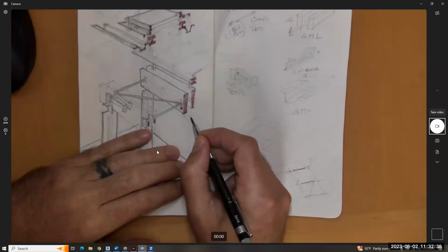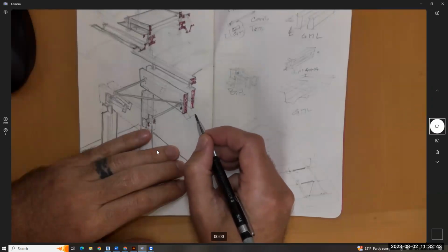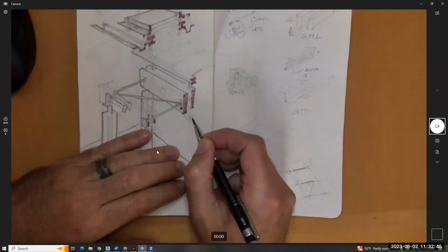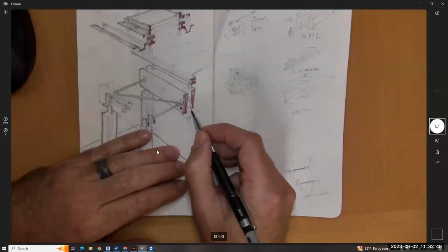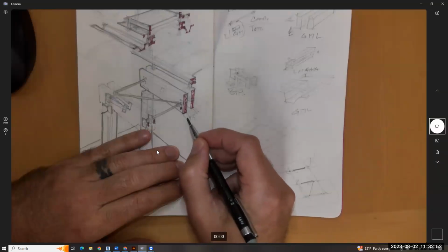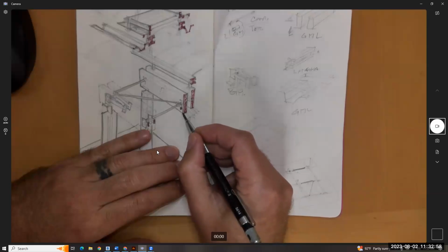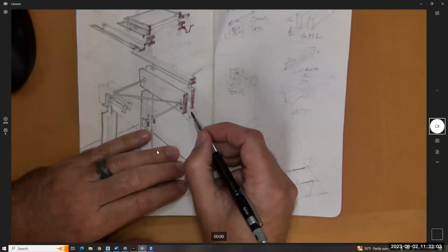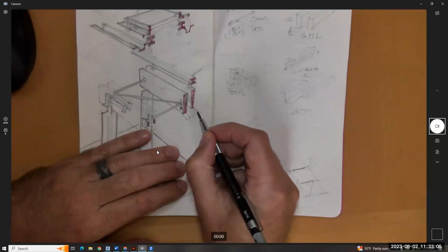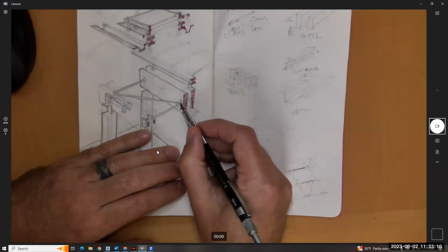So it's 8 inches for the width of the glulam. It's 16 inches, so it's 8, in essence 8, 8, 8, 8. Think of it that way, because the center line's in the middle, right? So that's kind of like the size of it, 8, 8, 8, 8, or 8, 16, 8, right? Which means we have 16 inches from the center line to the edge of that, which is kind of where this starts. So 16 inches, 1'4", is how far the inside face of that is, which is where I'm going to nest this node.